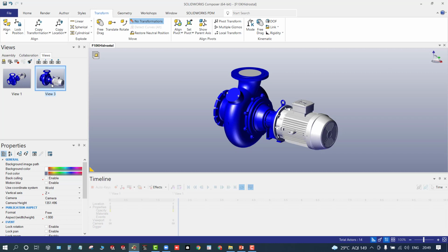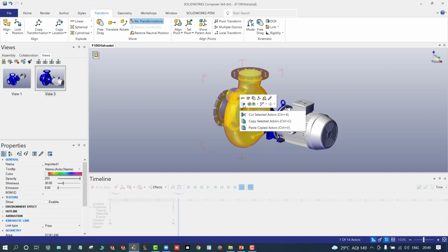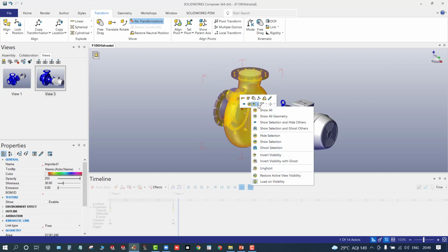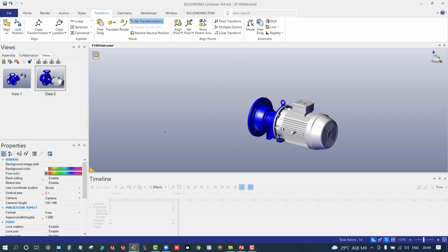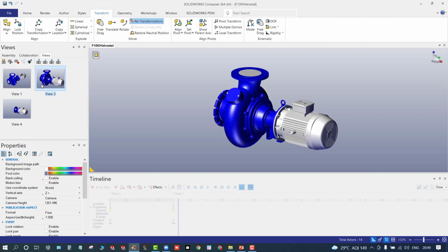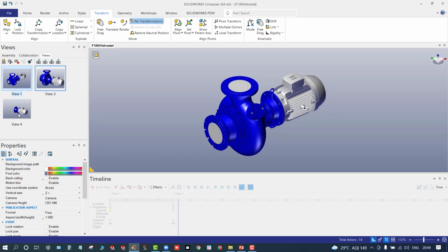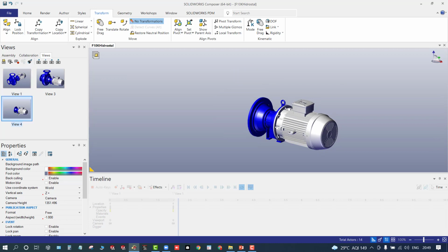There was a slight inconvenience with the component before. So here what you can do is you can simply hide the component which you don't want, as I showed before. Simply right click and select hide component. Once you do that, you can update the view by just selecting this option called update view. You could switch between the views like this. So now I need one more view. So in this, I'm gonna just hide this blue color portion in the front.